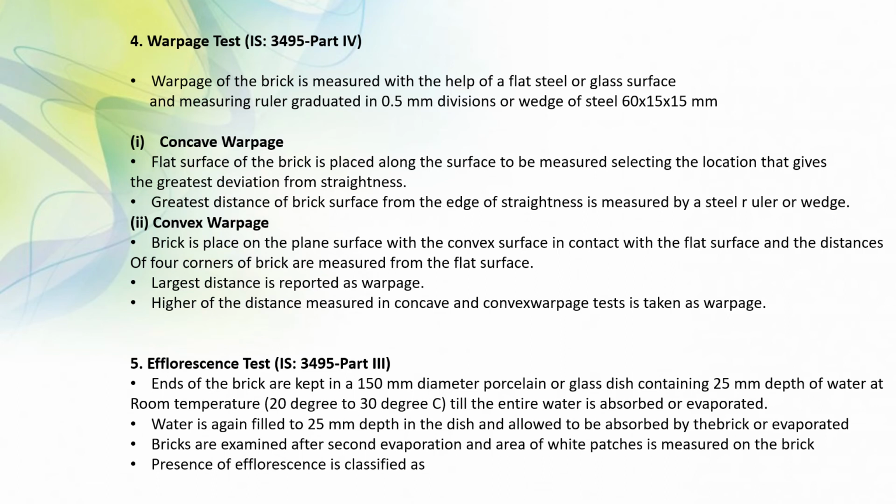Next, warpage test, IS 3495 Part 4. Warpage of the bricks is measured with the help of a flat steel or glass surface and a measuring rule graduated in 0.5 mm divisions, with a steel weight of 60 by 15 by 15 millimeter.